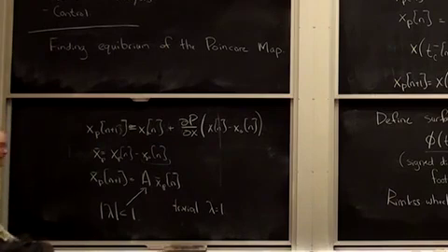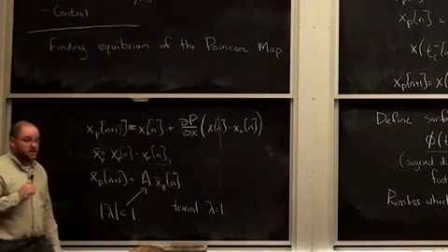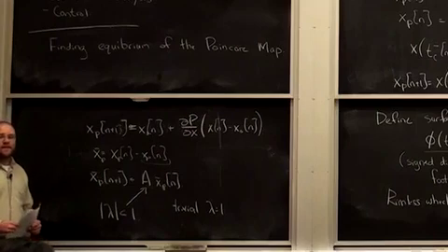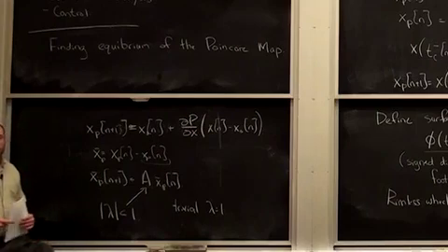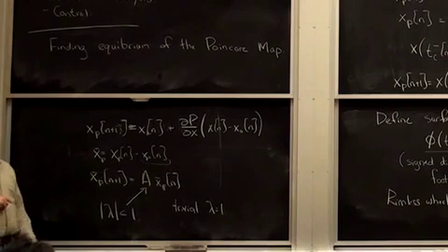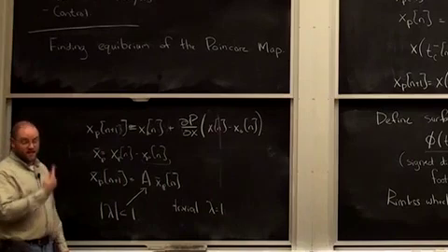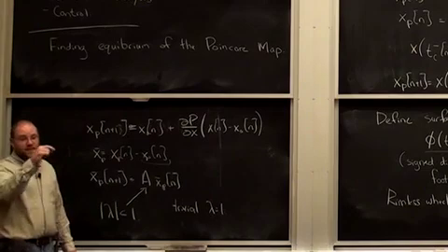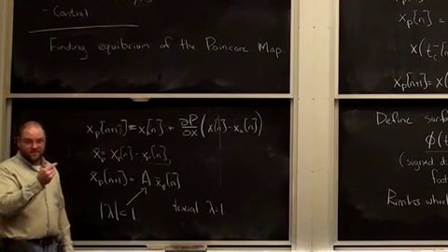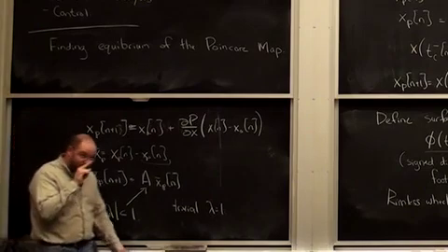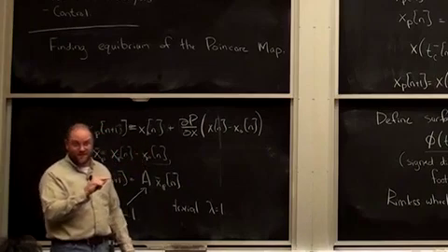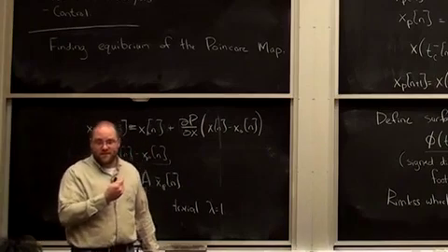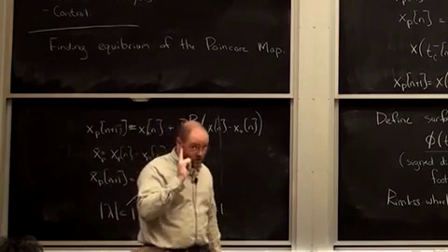Then there's some other direction that doesn't reject disturbances, and I start questioning whether it's stable. I wouldn't call it stable in the sense of limit cycle stability. If I could push in some other direction in state space and it doesn't get rejected, then it's not going to return to that orbit. There's just a special direction along the orbit which I'm allowed to push, and that's what defines limit cycle stability.